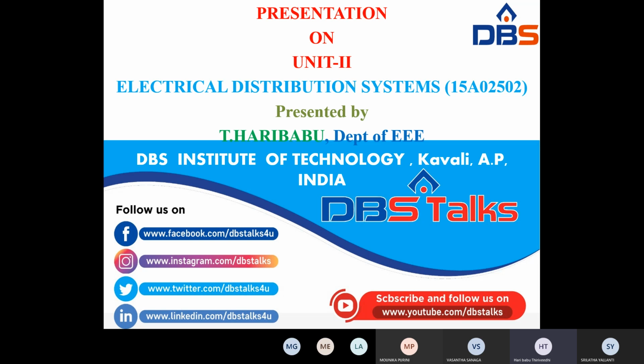So 230 minus 14 and 230 plus 14, that is 216 to 244 volts. In between these two, we can consider it a constant voltage. So depending upon the rating or voltage, there are the radial system, ring main system, and interconnected system.